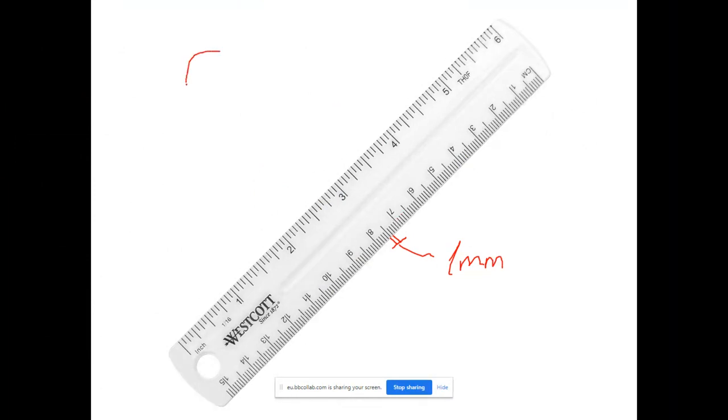Although in today's technology, for instance, on the technical drawing, we have a dimension and it is a functional dimension. It has been shown like this, for instance, 20, tolerance grade is H7. You know, in the format of today, we use IT tolerance grades.